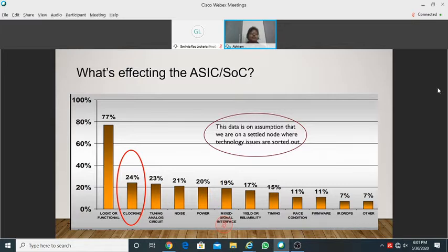So your processor operates at higher gigahertz frequencies, but your memories may not be that fast. So there are a lot of asynchronous domains here. The next part is the async domain crossings. That is where the failure rate is more dominant.